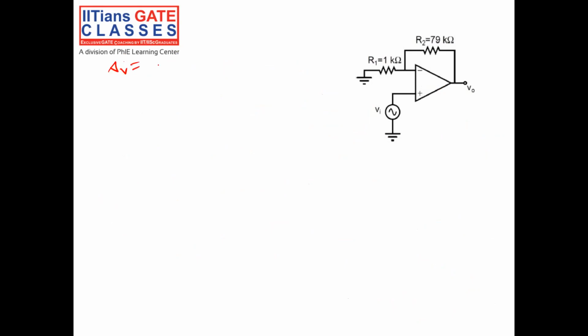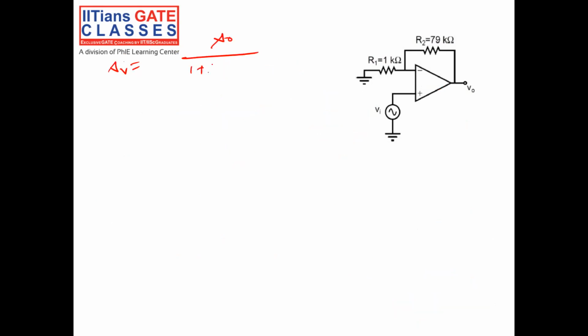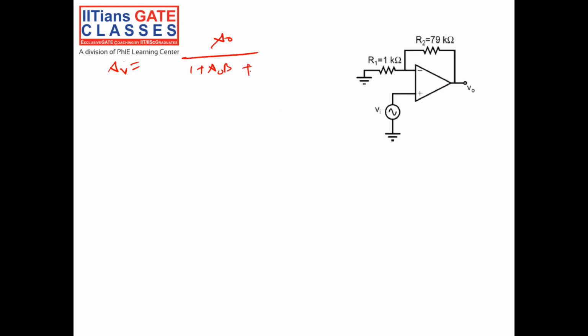So what I got is the gain Av equal to A0 above, and below I got 1 plus A0 beta plus j f by fc. So 1 plus A0 beta, here you see A0 beta, plus j into f by fc. If I take 1 plus A0 beta common, it will be A0 by 1 plus A0 beta, divided by 1 plus...